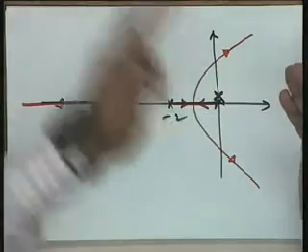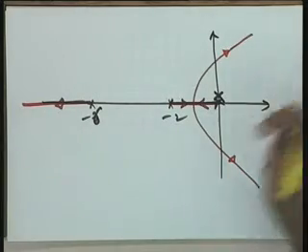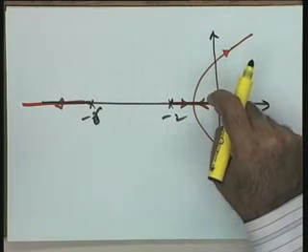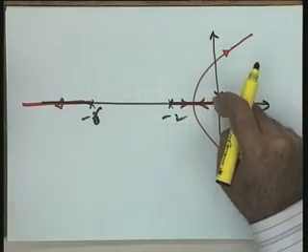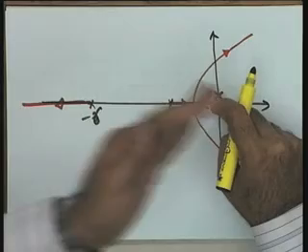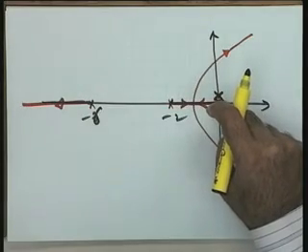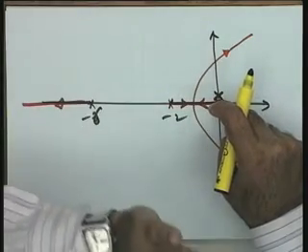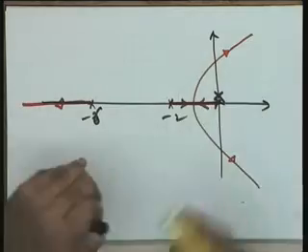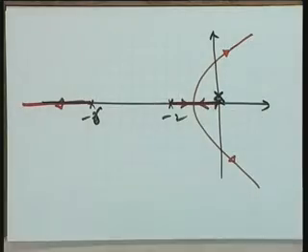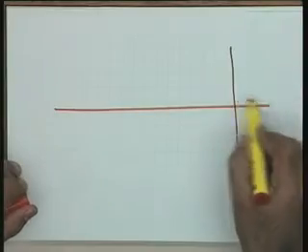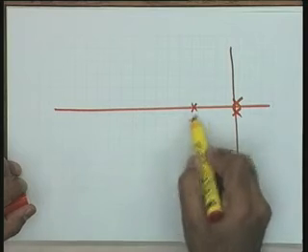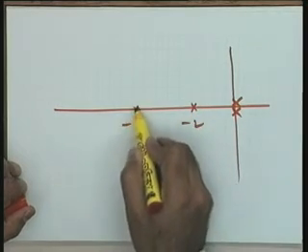But you have to keep in mind, you may be overdoing something. The user does not ask you for Kv equal to infinity, but you have given him Kv equal to infinity, fine, provided you have not disturbed the transient too much. Otherwise, he doesn't ask you for Kv equal to infinity. He says that Kv greater than or equal to 5 will suffice. But we have overdone it as far as the steady state requirement is concerned. And let us see what is the price we are paying. Come on, tell me, what is the price we have paid? Anyone who has made a sketch of this? What is the price we have paid by this selection?